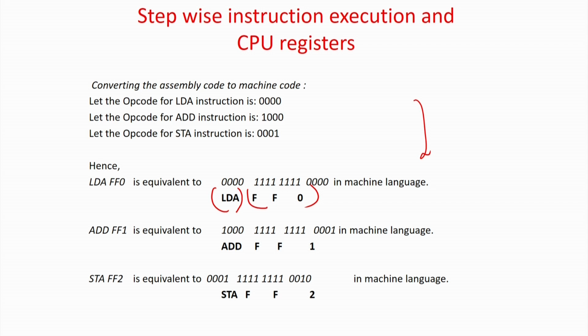Maybe this machine has 3 instructions, so 2-bit codes would have been enough, but let us assume that the machine has more, say 16 operations, so they have kept 4 bits as the size of the opcode. So the codes for load, add and store are these: the opcode 0000 means a load instruction, add is 0001, and store is 0010.